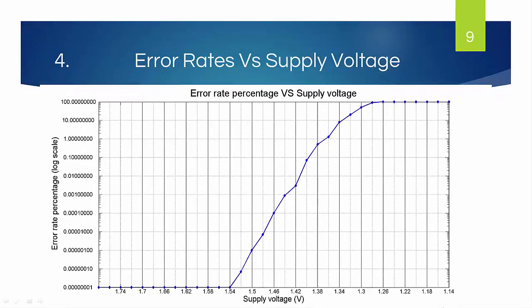The picture shows two important design points: no margin, the lowest voltage that can still guarantee error-free circuit operation, and full margin, the voltage at which the circuit runs without errors in the presence of worst-case process variation and signal noise. Traditional fault-avoidance design methodology sets the circuit voltage at the full margin point.